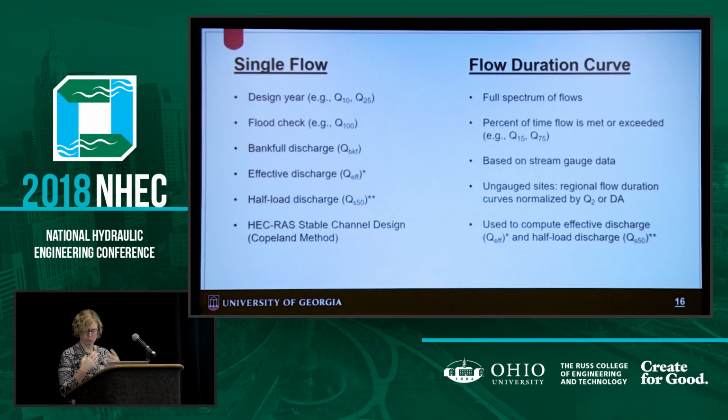So your Q10 or your Q25 that you've been using, your flood check, your Q100 or your Q50. Bankfull discharge is another example of a single flow. Effective discharge, half-load discharge, those are similar to bankfull. And then, like I mentioned, the HEC-RAS stable channel design is also based on a single flow. On the other hand, you have a flow duration curve. This is the full spectrum of flows. We're not talking annual maximums, we're talking daily, hourly, and even, if you have it, the 15-minute interval. So everything you can give me from the USGS gauge station.